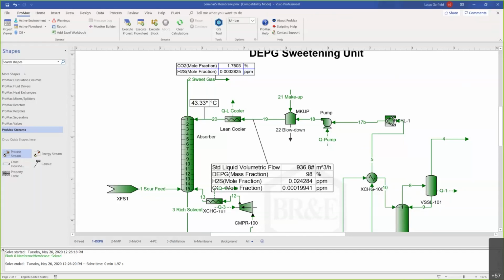You're going to have lots and lots of CO2 that comes out of the ground with the oil if you're injecting CO2 in the reservoir for EOR. You're going to have to deal with that CO2 later on. Flue gas is an obvious one to think about, power plant flue gas. And then perhaps biogas would have CO2. I'm not really sure on that one, but there's lots of different places that you could encounter CO2 in a gas stream.